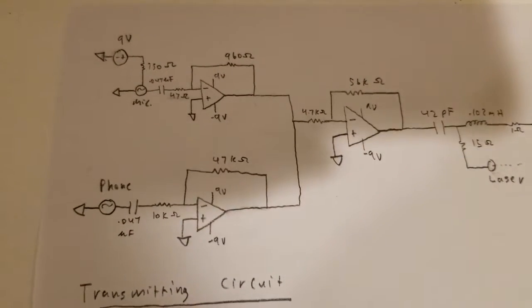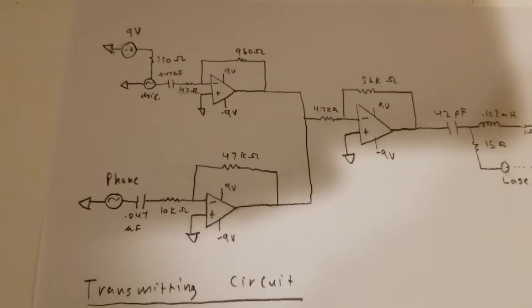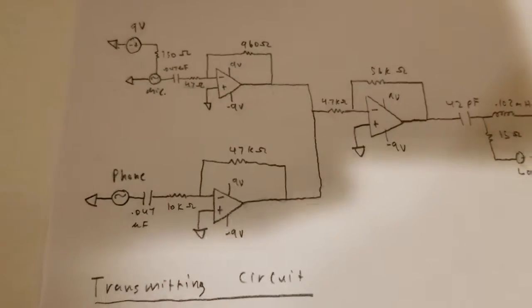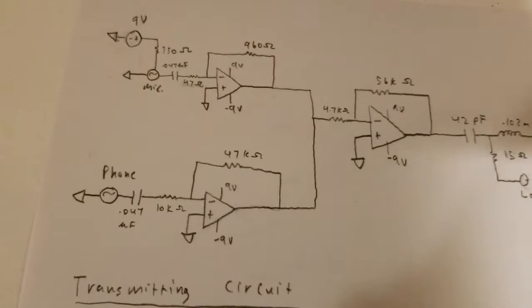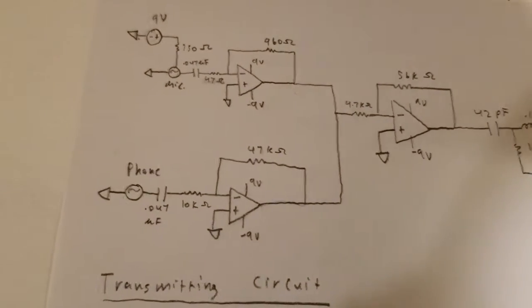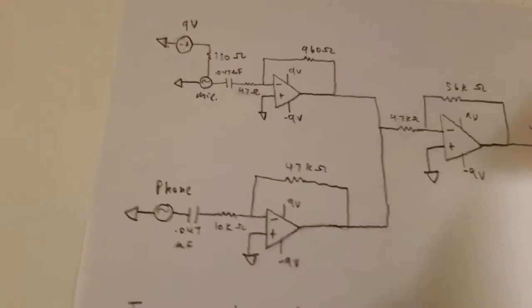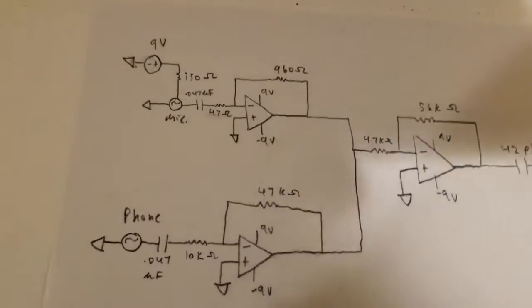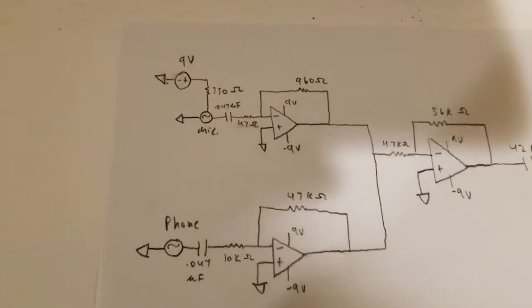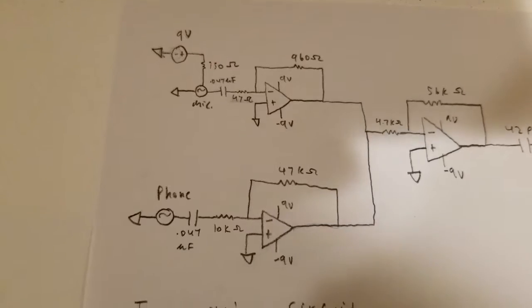So we aimed for about between 30 and 40 hertz as a frequency as a minimum, because those lower frequencies can usually cause a lot of noise. So after that frequency, you get a lot more clearer sound. So we did those right before the amplification, so that going into the amplification, we had a really clean signal.